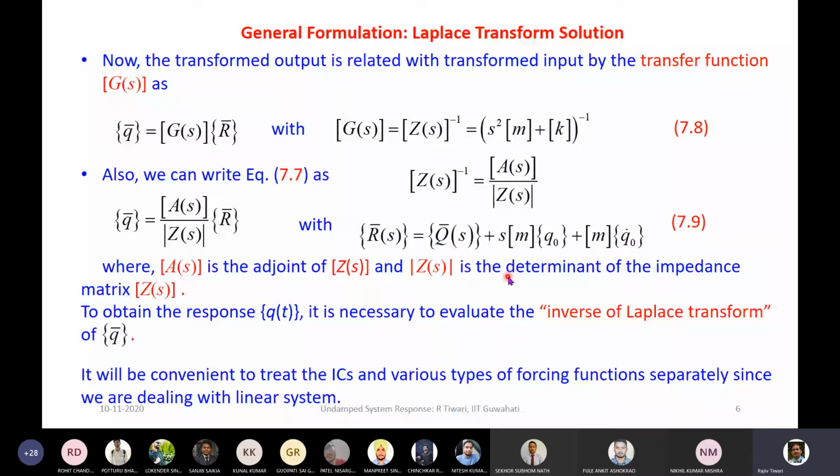Even in this particular force we can have different kinds of forcing, like harmonic force, which is the simplest force, a sine function or cosine function, or we can have periodic force, in which case we can split that into various harmonics using Fourier series. So periodic force will be nothing but the summation of various forces with different excitation frequencies and their multiples.